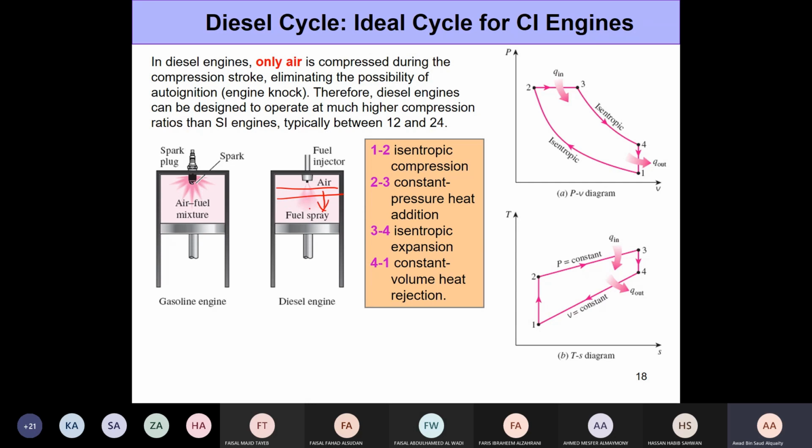But the piston is already in the expansion stroke or the power stroke, so it is already starting to go down as the ignition happens. So as the ignition happens, the piston is already moving, so the pressure remains more or less constant. You can think of it as some sort of a free moving piston. Okay, you're adding heat, of course, but the volume is also increasing.